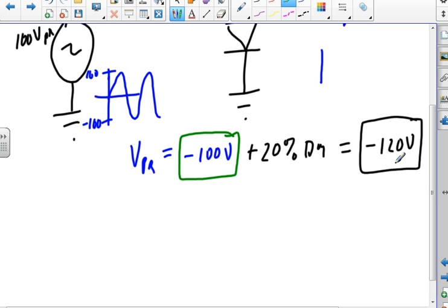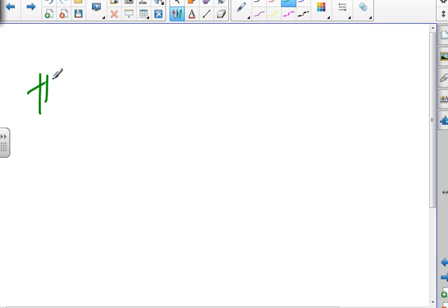Okay, so that was 14. 22. A silicon diode has a bulk resistance of that. At what value of forward current will the value of VF, the forward voltage, equal 0.8? All right. 22. So did I get the 22 right? All right, so I've got... Those look like fancy ones to me. I got 20 ohms.